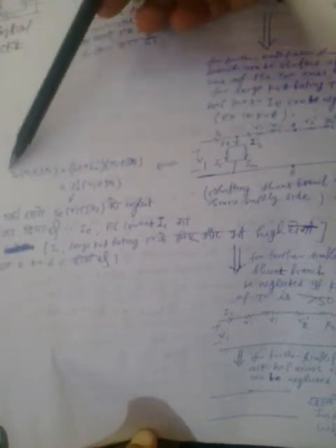By doing this, the drop due to primary current in the primary impedance, I1 times R1 plus jX1, in place of I1 you write IE plus I2 dash. So now this is I2 dash times R1 plus jX1, right?